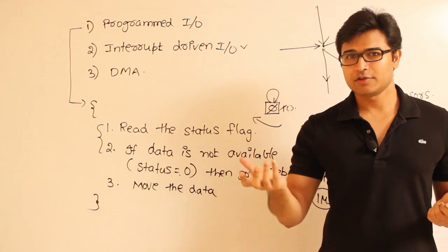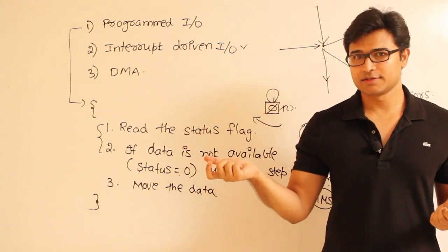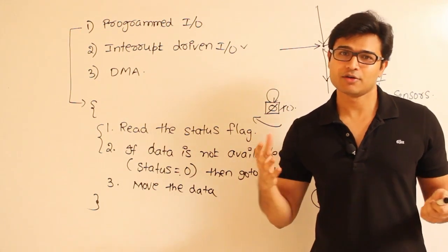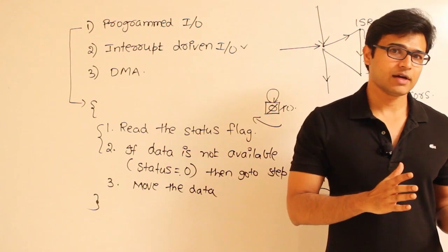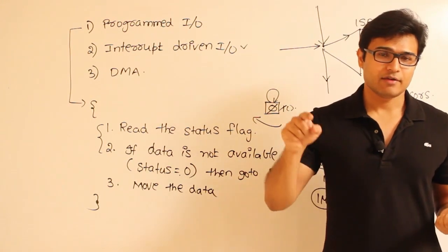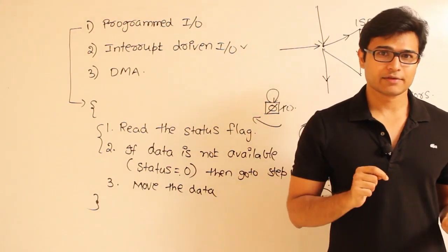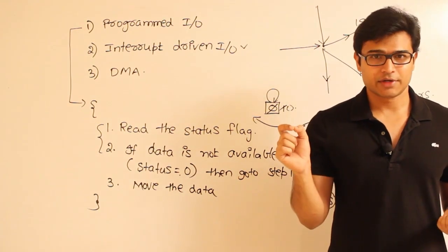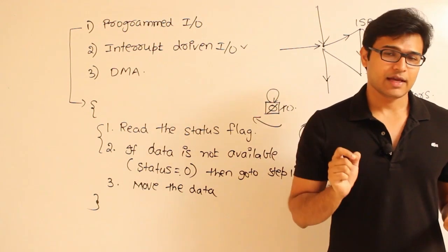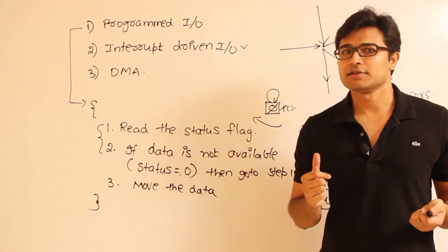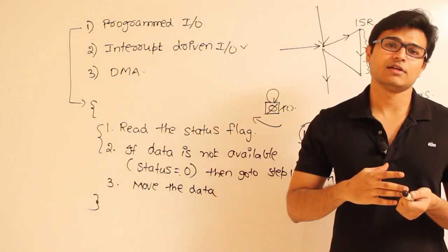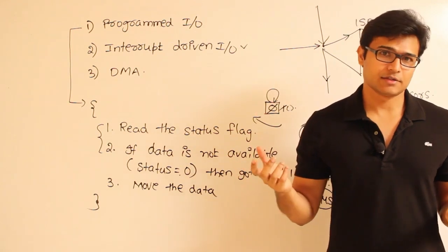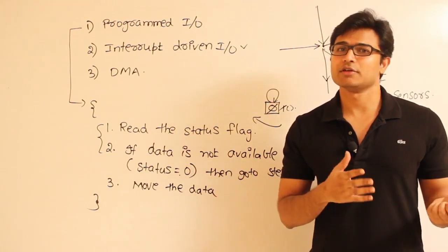the RAM, the status of the memory, has to be saved in the hard disk. Otherwise later when you try to reboot it, you will not be able to get your present work. So all the current work has to be saved, right? In that case, whenever you try to turn off the computer, there will be a trigger, there will be a sensor there. So your CPU will be triggered by this particular sensor, and it will say that someone is trying to switch off the power, or let us say the power is suddenly off because of a power cut or some external disturbance, suddenly the power source is not giving you the power.